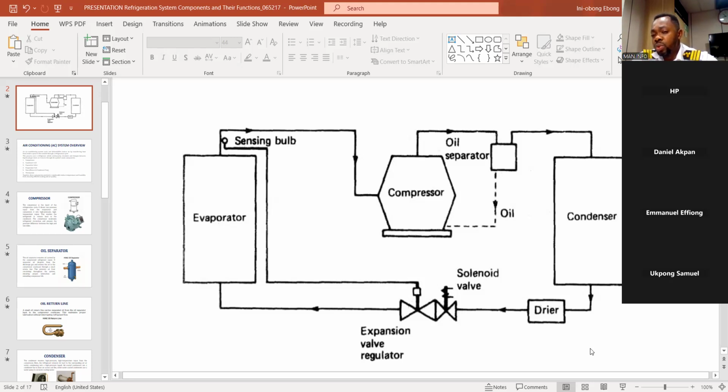For you to be able to know if your capacitor is bad or good, we have a dual capacitor and a single capacitor. The dual means that capacitor will have three terminals. One will serve as your common, one is marked F, and the other they will write either COM or H. That H means hermetic compressor, that is where your compressor is supposed to be connected. The F means fan, where your fan is supposed to be connected. The common is the current that comes into the capacitor.